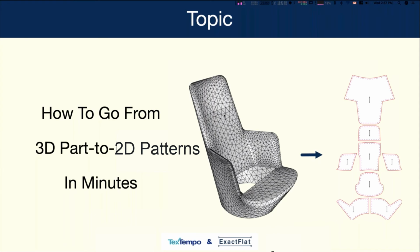If there's a shrinkage factor, you have two choices. You can either shrink your model by a certain percentage, knowing that you're going to have some strain in your part afterwards, or you can tune, or true as they say, the 2D pattern pieces after the fact. That's a strategy that many of our clients do. And if you want to know more about that, we can certainly talk more about that offline. That's a bit of the science meeting the engineering there.